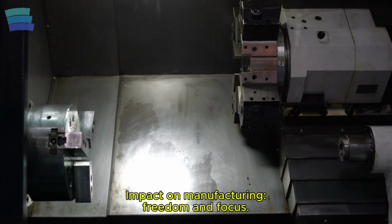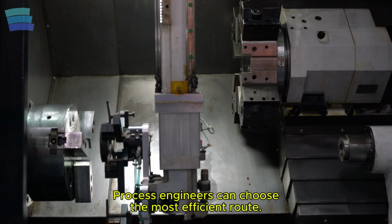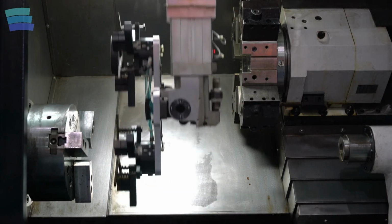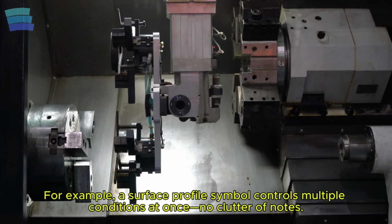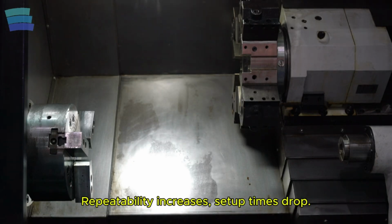Impact on manufacturing. Freedom and focus. Within the framework that GD&T provides, the process engineer selects the most efficient method. For example, by using a profile tolerance, you can control a surface with a single symbol instead of a cluster of notes. Operators don't get lost in complex annotations.